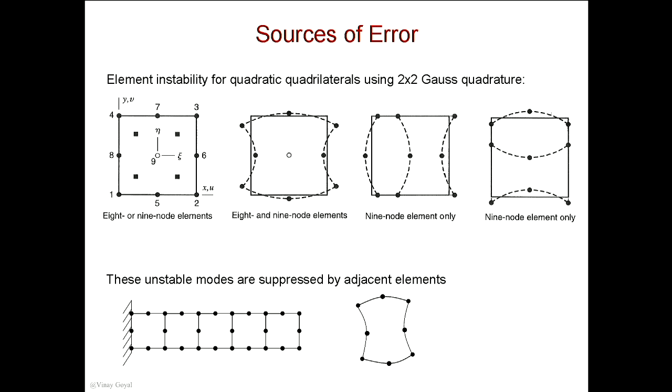Excellent. Don't think that with second order elements you don't have problems, because you can have problems too. So with 4 quadrature points, I want you to check with me whether it's possible. These are the modes, some of the modes, not all of them, for that element. If I'm an integration point about here, can I sense movement there? Can I sense movement there? No. Can I sense movement? No. You won't be able to sense movement, and it's going to cause this weird element deformation sometimes. So you want to watch for that as well. These elements suffer from the same things too.